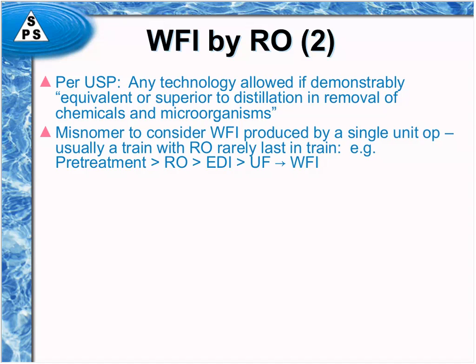So there's often either plain bottle-type DI or electrodeionization of some sort, and perhaps even ultrafiltration downstream of that to remove any residual endotoxin that may not have been pulled out by the previous 2 steps.